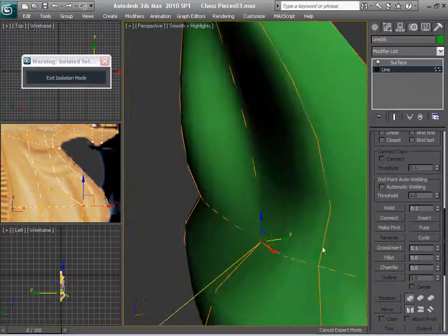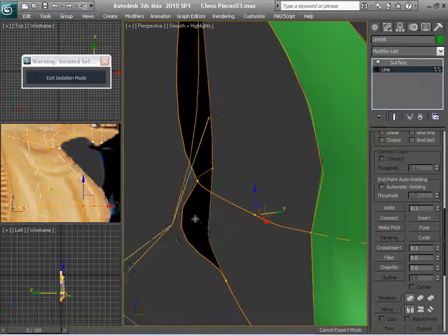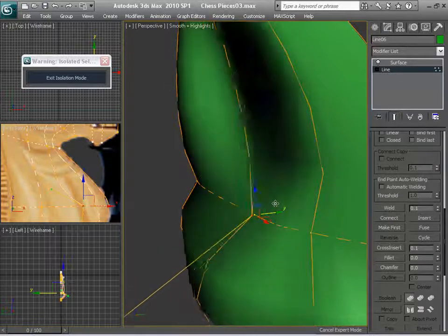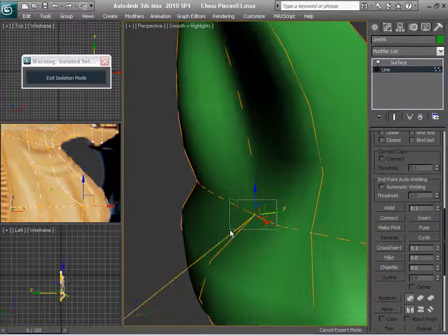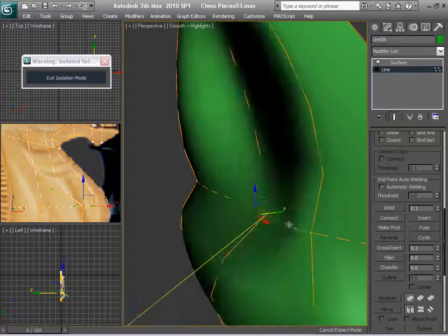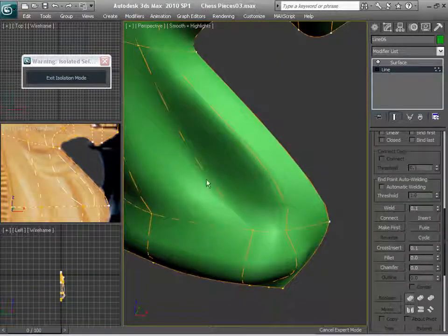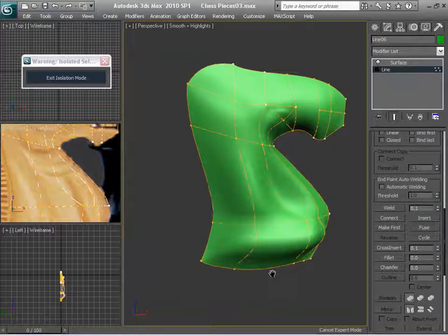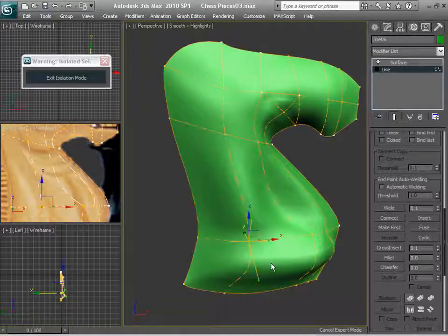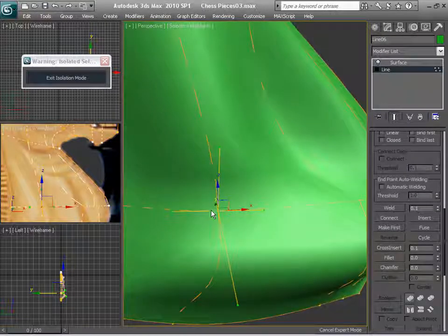In there we have several vertices, and if I push one out, you can see how that patch breaks. So in general, you have to make sure that you select by dragging a rectangle, so you can select all the vertices together, because there's not only one in there. There's 2 vertices, one for the line that goes vertically and the other one for the line that goes horizontally. So in this case, you want to make sure that you're selecting both vertices, and you know that you're selecting both because you get 4 handles instead of only 2.